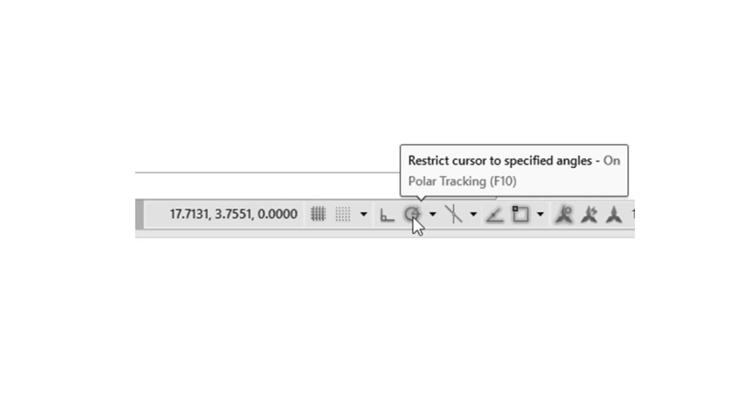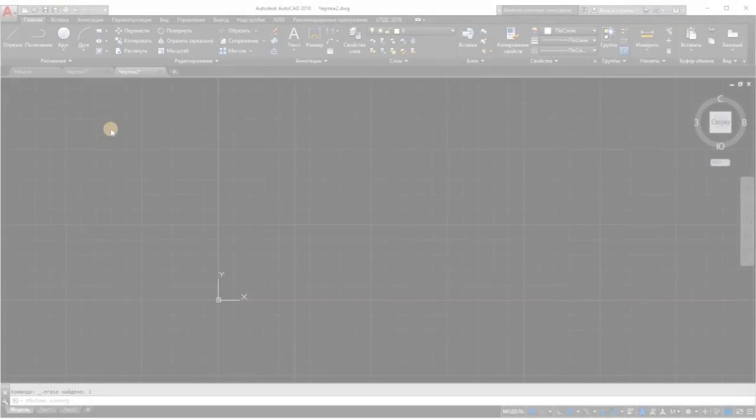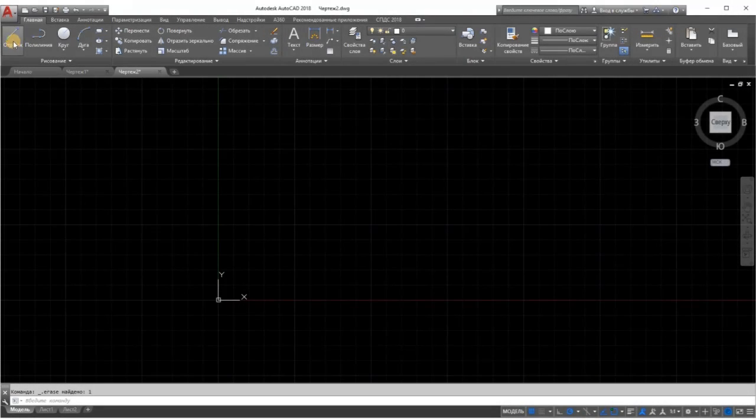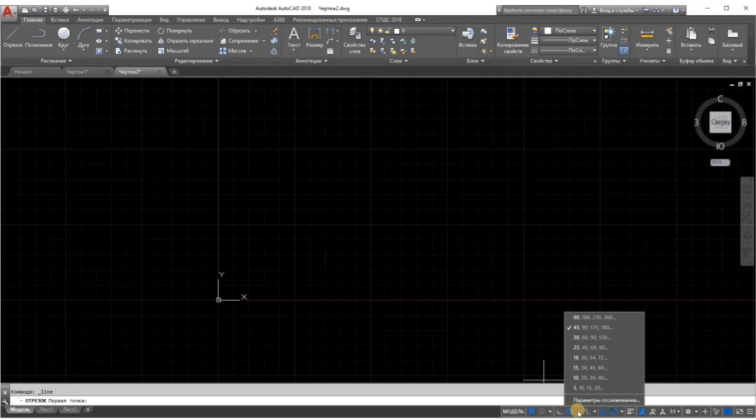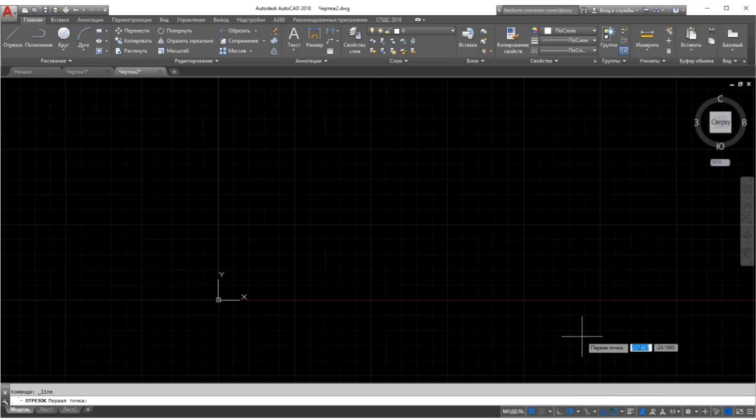Five, if the line you drew isn't the exact length you want, you can back up during the Line command and change it. To do this, type U and press the Enter key. The line you drew previously rubber bands as if you hadn't selected the second point to fix its length. And finally, right-click and select Enter. This terminates the Line command.